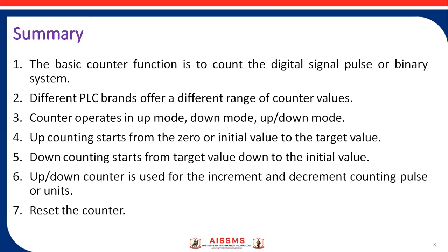In a nutshell, the basic counter function is to count digital signal pulse or binary system. Different PLC brands offer a different range of counter values. Counter operates in up mode, down mode, and up-down mode.